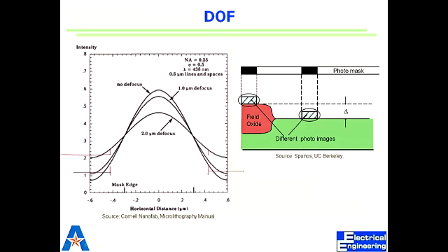So for this guy, now you have your intensity up here, then this guy where you would have your intensity here. So now your resist is going to get developed. And if this is the threshold, maybe you'll have a wider line, a wider square exposed where you wanted a small one to be exposed. So maybe you are shooting for 1 micron by 1 micron, but you will get 1.2 micron by 1.2 micron. Make sense? Unless you focus on that level, then maybe you'll be getting out of focus somewhere else. And 1 to 2 micron is small, so your feature will be obviously of the same scale.